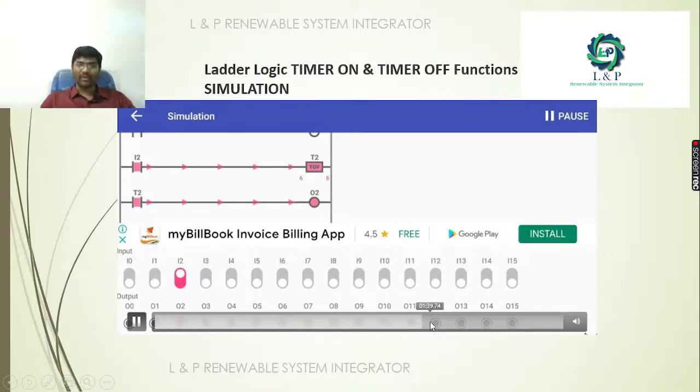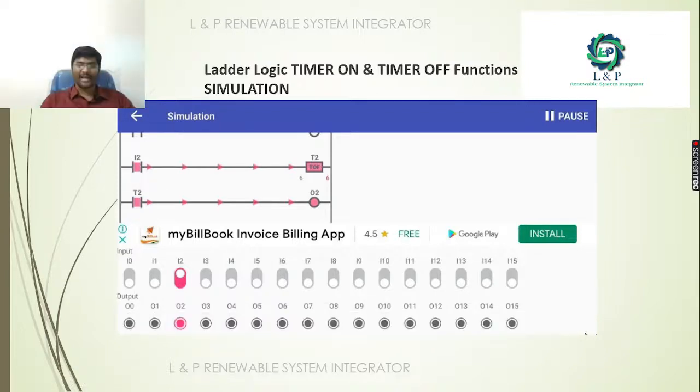And when we turn it off, what will happen? See here, it does not switch off when we enable the switch. It gets affected only when input 2 is turned off. See here, 6, 5, 4, 3, 2, 1. Immediately the output will be off once we get the done bit. So this is how the off delay timer works.